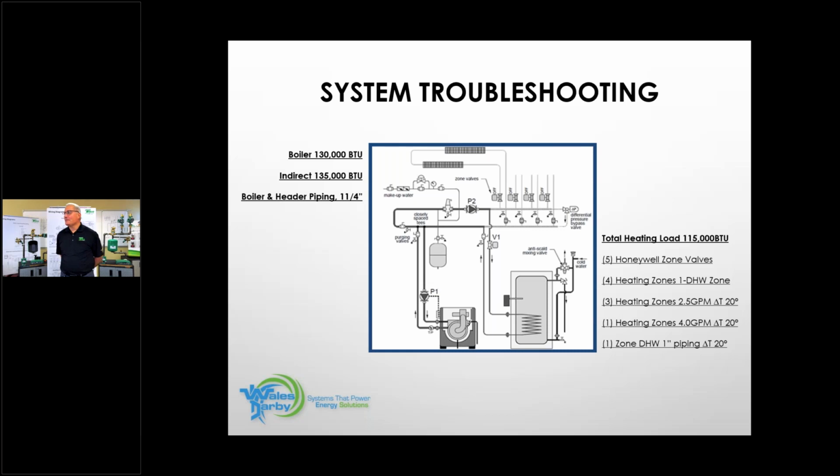Oh, excellent here. Little Sally only has 35,000 BTU going to her room. Fantastic. And the domestic hot water tank only has 35,000 BTU going to it. Fantastic. So Sally in her room is not happy, and Sally in the shower is not happy. Poor Sally. But our job is to make Sally and all of our customers comfortable, and whoever put that answer in is absolutely dead nuts on. That gentleman knows that a standard Honeywell is only a 3.5 CV through the valve. That's 35,000 BTUs. You're 5,000 BTUs short.